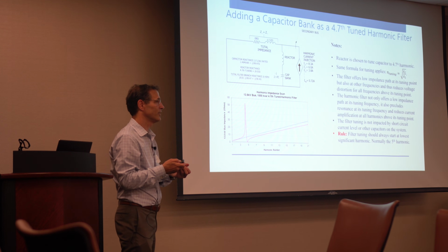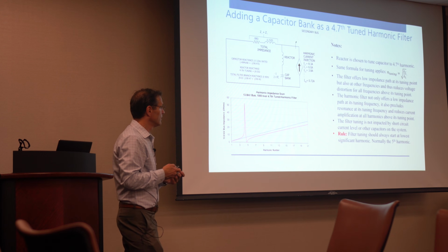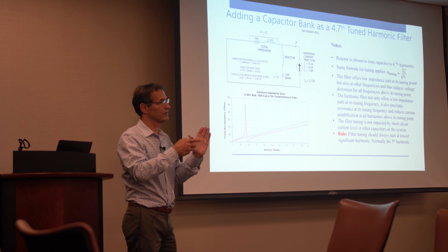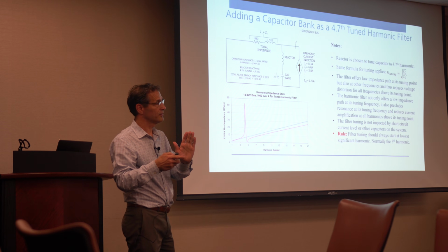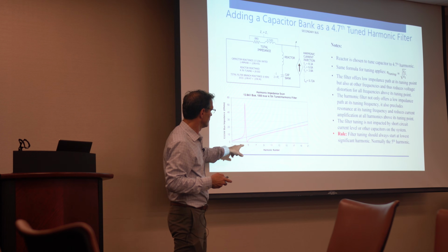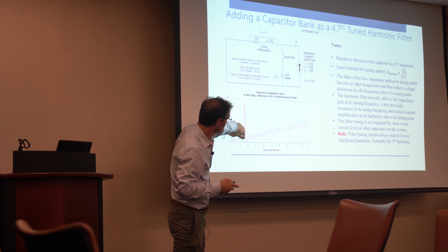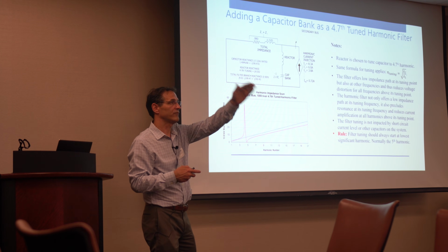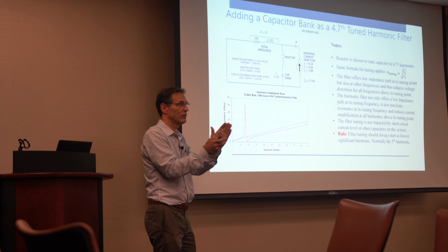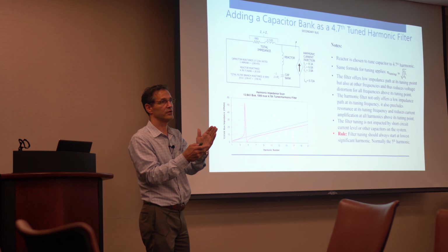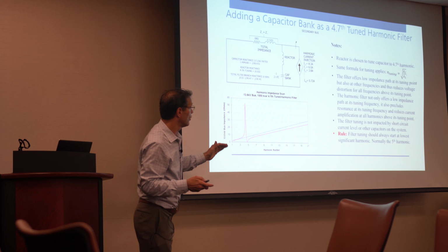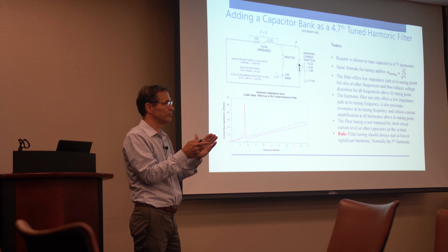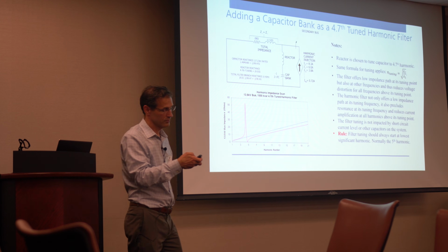So you tune below. But sometimes for your analysis, you need to filter every bit of amps you can, and you do that by tuning straight on the frequency. Sometimes I will design the filter so it's tuned above the harmonic, especially in the multi-tuned filters, where the slope of the impedance curve might come down slow, but then come up fast. I'm better off to tune above, because a small variation is a small change in my impedance of the filter. So it's not always the case that you design your filter to be tuned below frequency. Sometimes you go above.